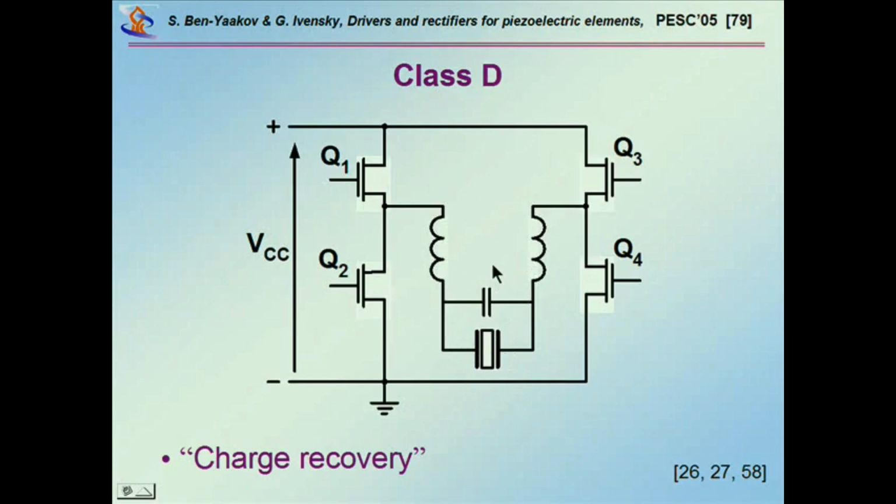So basically you have an inverter that is generating these voltages. You can run it at fairly high frequencies, say 200, 250 kilohertz. This is what is done today, to generate, say, 1 kilohertz. So you have a nice waveform after filtering at the output. The problem is that you still have some ripple, and this ripple generates fairly high ripple current in the device. But in simple applications, this is a good solution.